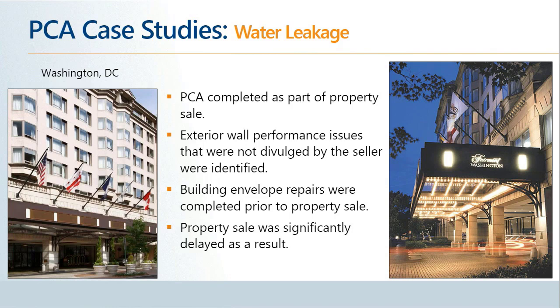And during the course of these interior surveys, conditions indicative of uncontrolled water leakage were identified at several of the hotel rooms. This included staining and damage to interior finishes, as well as damage and staining on interior finishes, specifically drywall that had been removed as part of the hotel renovations, and interior finishes, specifically wallpaper, that were removed during the renovation program.